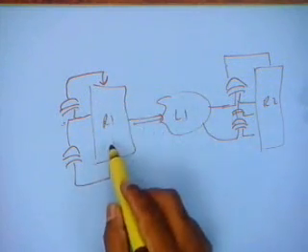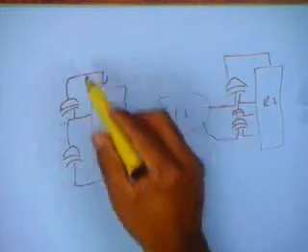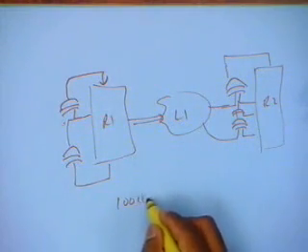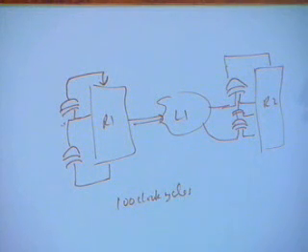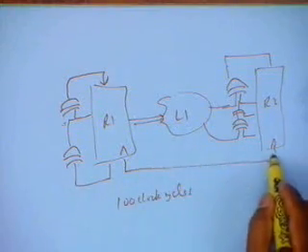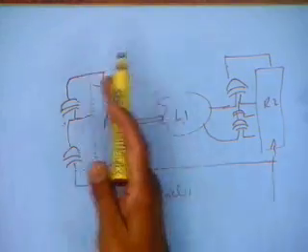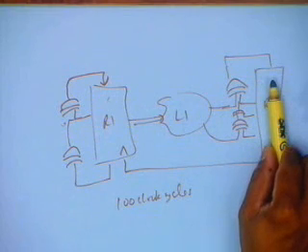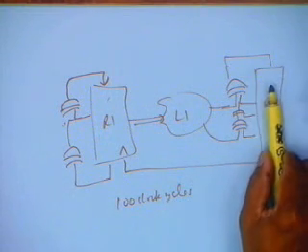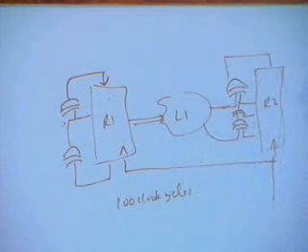So I start from a seed and run this generator, let us say, for 100 clock cycles. So I will get 100 fixed, same input patterns. They are random, but they are the same pattern each time because I am starting from the same seed. And I am now running both of them together, clocked by the same clock, for 100 clocks. Again, I have initialized this to some value. After I run it for 100 clocks, I will have some bit pattern stored over here, and this bit pattern is the signature of this logic.